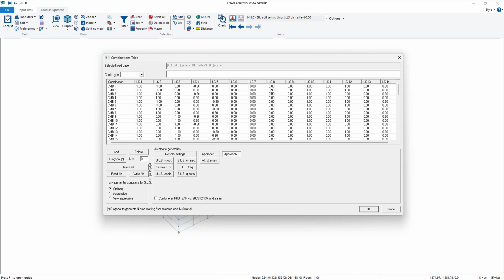And then we can see what other kinds of loads are applied. The static one, basically, so the static pressure load for the soil that has been inserted inside this load case. And then we add the factor one for load case 12, which is the ETK, so the soil dynamic pressure in direction negative for alpha 0, so in the direction x negative.